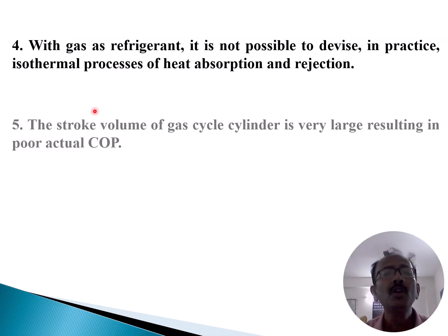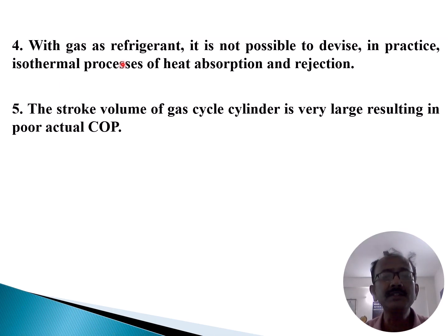Number four, with gas as a refrigerant, it is not possible in practice to devise isothermal processes for heat absorption and rejection. And number five, the stroke volume of a gas cycle cylinder is very large, resulting in poor actual capacity.